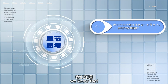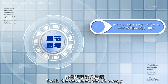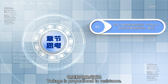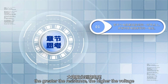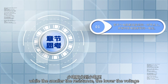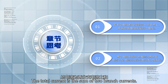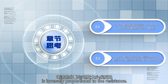Through the above study, we know that resistance is an energy-consuming element. That is, the consumed electric energy is changed into heat energy. For series resistance, voltage is proportional to resistance. In other words, the greater the resistance, the higher the voltage, while the smaller the resistance, the lower the voltage. When two resistors are connected in parallel, the total current is the sum of the two branch currents, and the distribution of current is inversely proportional to the resistance.